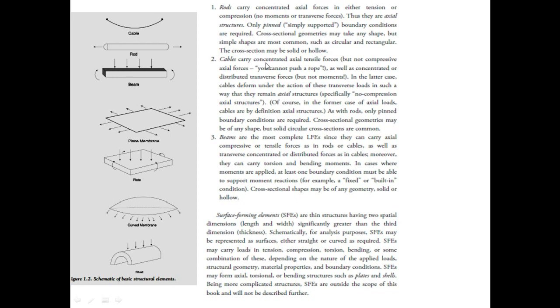What about cables? They carry concentrated axial tensile force but not compressive. You cannot push a rope. Again, that's very logical. If you have a rope and you try to push it, no one in this world can do that because it has a tensile response. So the cable deforms under the action of transverse load in such a way that it remains an axial structure.